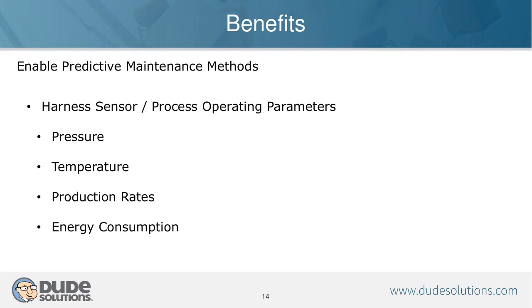And a system can help you improve by understanding what you're doing. The next step is you want to make sure that you're trying to implement a preventive maintenance schedule. And as we've said before, that could be something that's on a calendar basis, or with the Industrial Internet of Things, you can start to implement a usage-based preventive maintenance program.